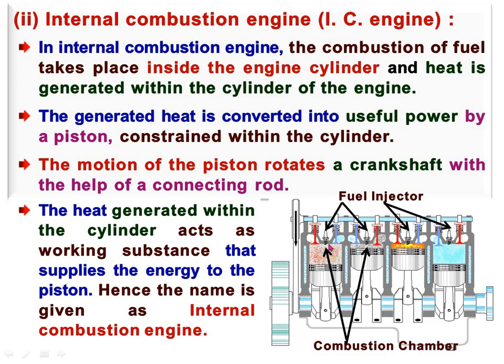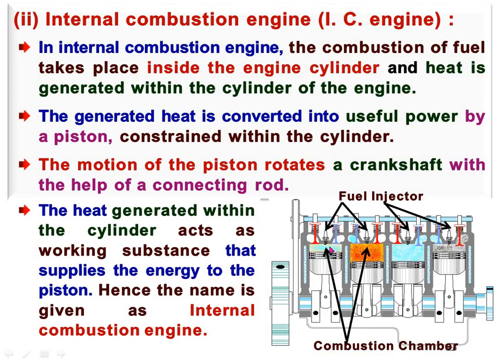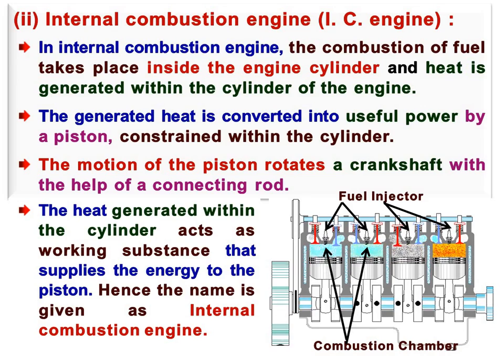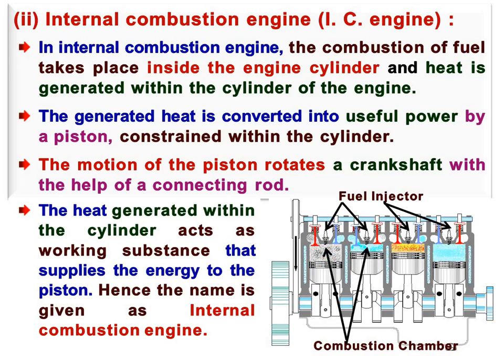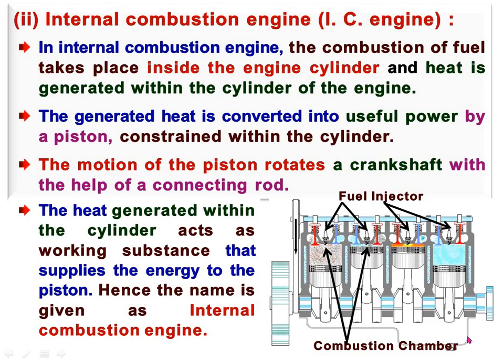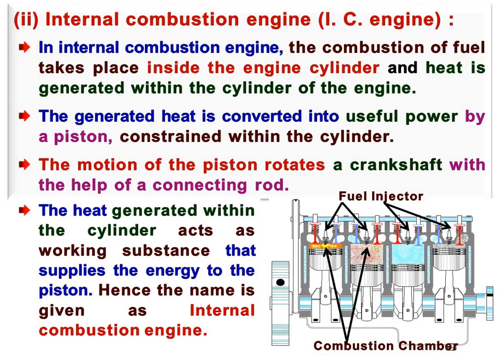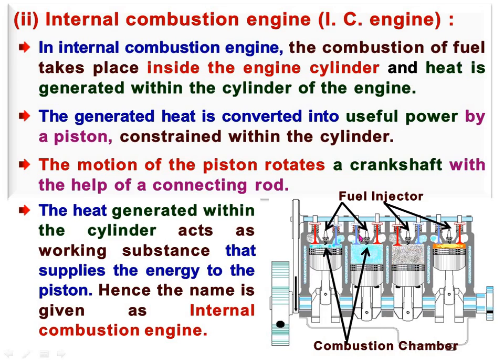This fuel injector injects the fuel at the proper time into the combustion chamber, and this fuel is burned due to the highly compressed air which has a high temperature. So in a compression ignition type of engine, there is no need for a sparking arrangement or any other arrangement to burn the fuel.